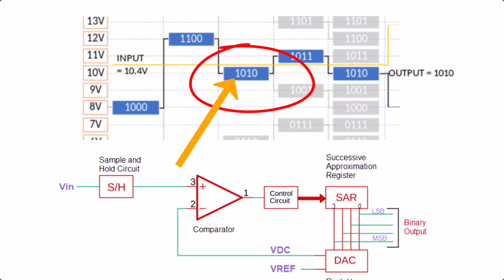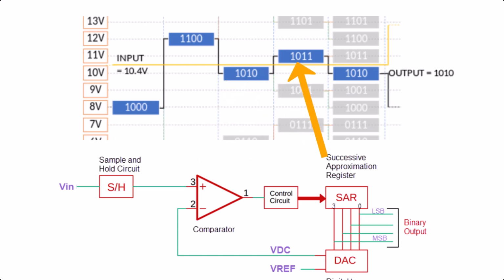And it puts then a 1 again, and then you drive the output voltage a bit closer, at 10 volts, but you still undershoot, and the control circuit says, okay, you are closer but you need to get even higher. So then you keep that digit and you drive a next cycle, you add a bit more voltage, and that way you shoot over and under until you find the right value, or you run out of bits.